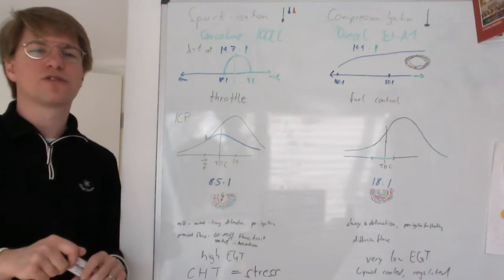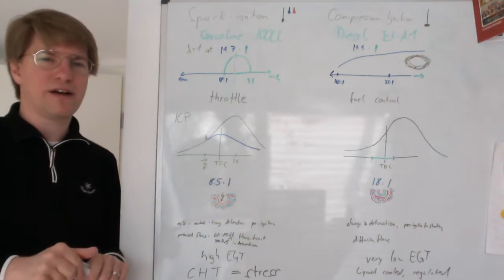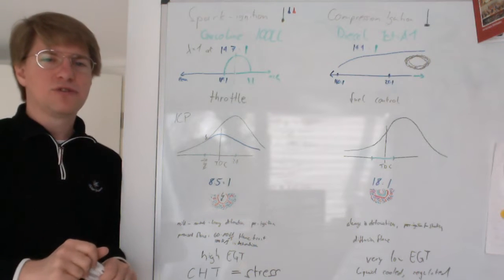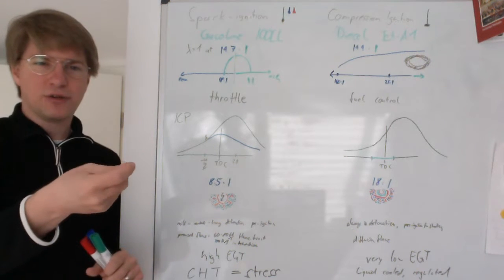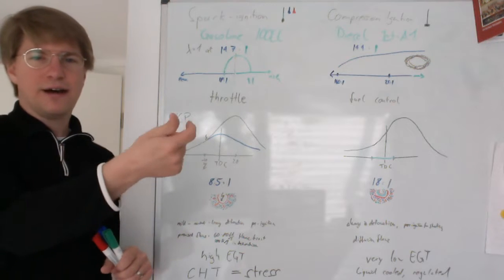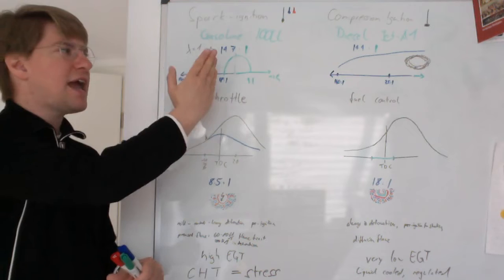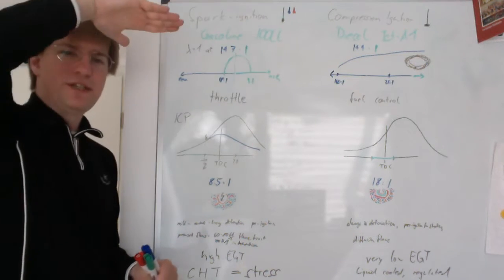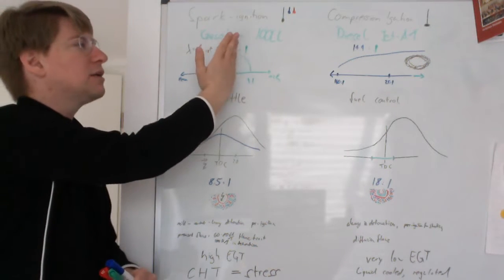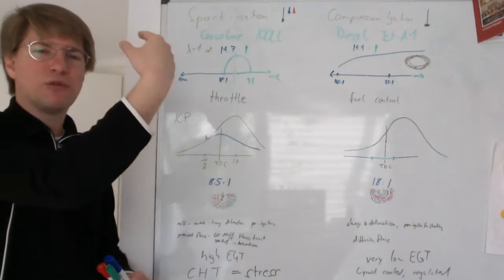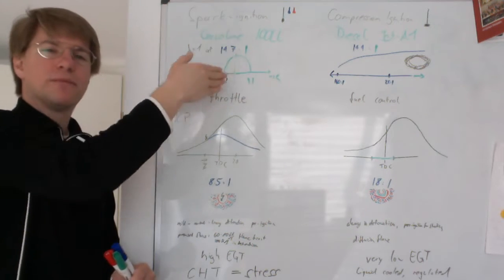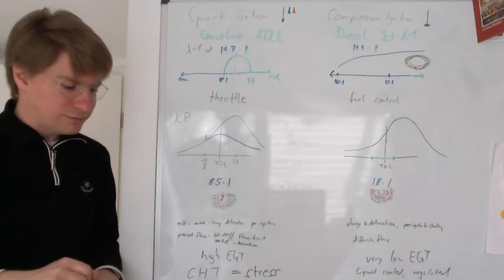And that is why it's crucial in normally aspirated aircraft, as you climb into higher altitudes, to pull back the mixture control knob. You need to lean out the engine to reduce the amount of fuel going in, to keep the weight of the fuel and the weight of the air in the burnable range.